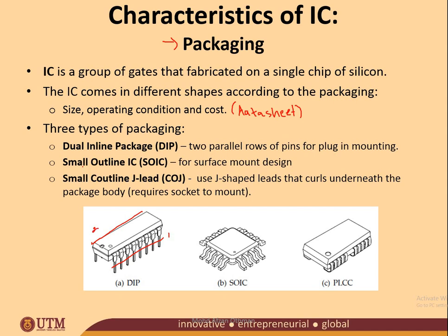And then the other type of packaging is small outline IC. This is for surface mount design. And small outline J-lead, SOJ, uses J-shaped leads that curl underneath the package body. So this one requires a socket to mount.